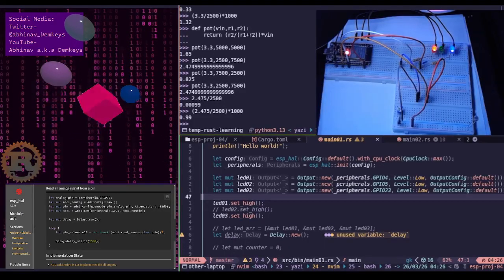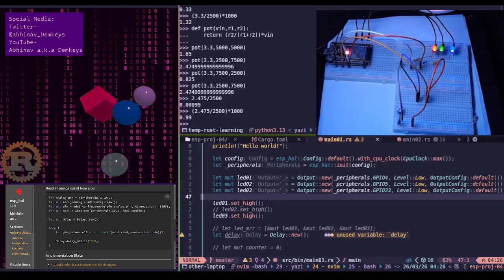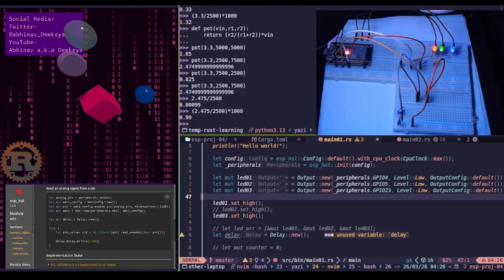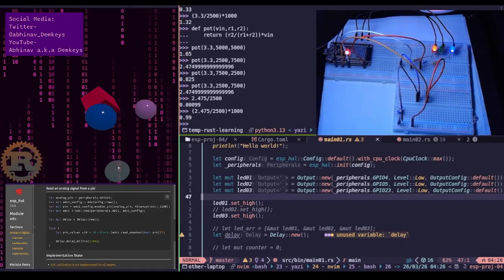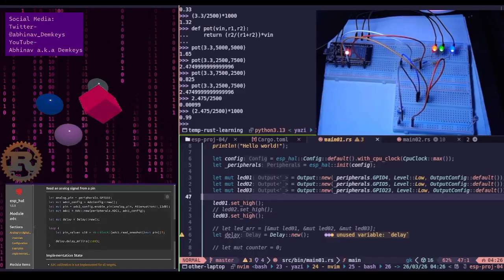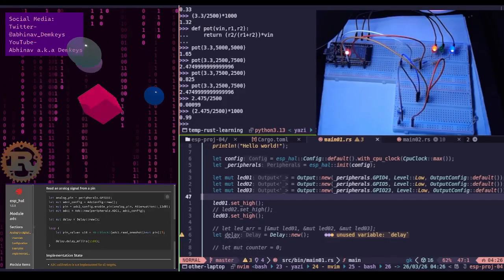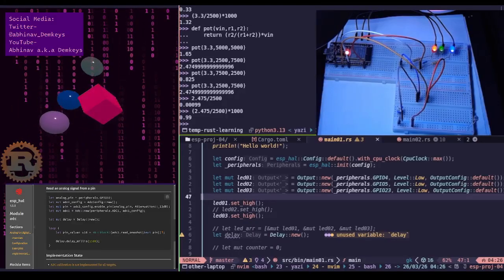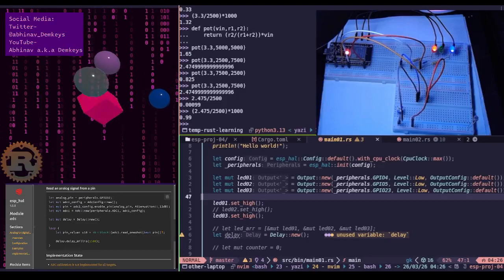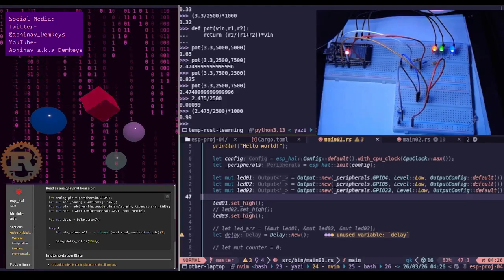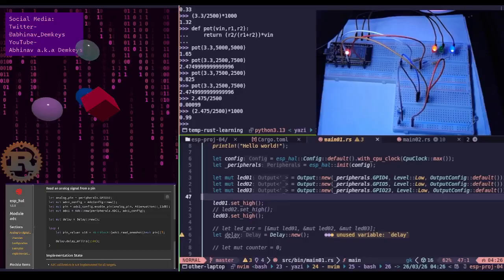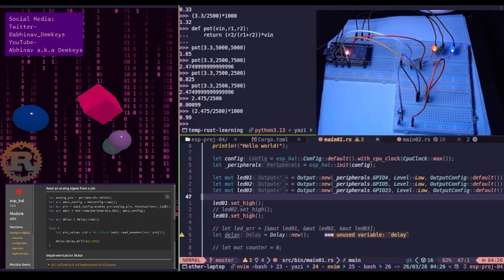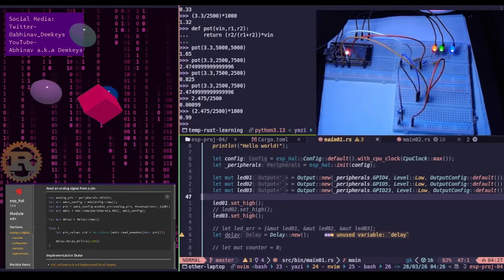Okay, so 0 dB is around 1.1 volt, 2.5 dB is up to around 1.5 volts, 6 dB is up to around 2.2 volts, and 11 dB, often called 12 dB, reads up to around 3.3 volts. That's why I have to set it to 11 dB. But I kind of want to get an understanding of why exactly this is.